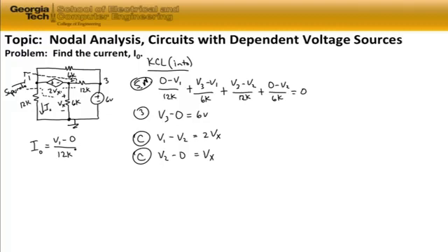So if we use our 4 equations that we have here and solve for V1, we end up with a V1 which is equal to 9/2 of a volt. If V1 is equal to 9/2 of a volt, then we can find I0, and our I0 comes out to be 3/8 milliamps, simply by plugging in our V1 into our equation for I0.